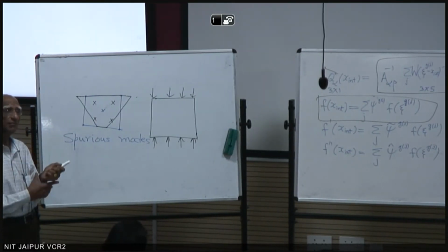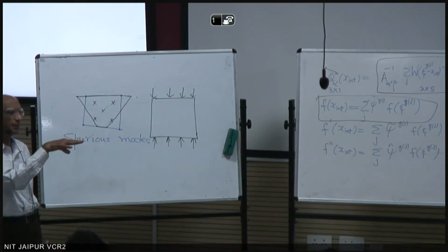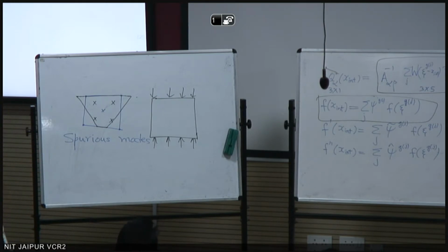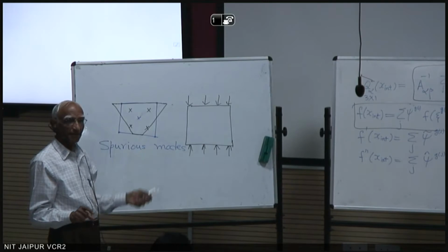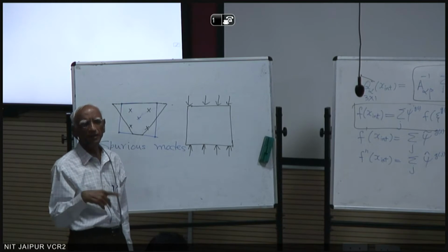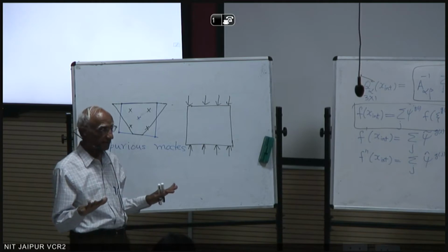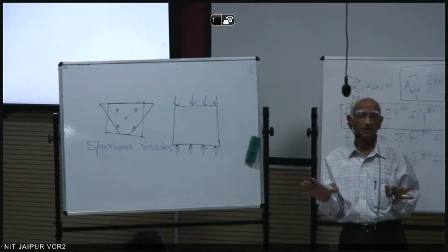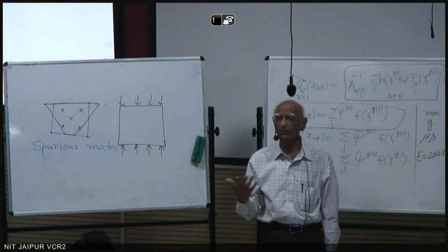I don't know whether I have downloaded the paper on my computer or not, but it's in one of the papers with Guy Manton. He checked the code and did that test. With the default algorithm, you get 7 different curves. With the Belytschko-Bindeman algorithm control, you get the same curve for all those 7 elements. So that tells you which control algorithm you should use in LS-DYNA. If you are using Abaqus, that is a different story. You possibly have to use a different algorithm.